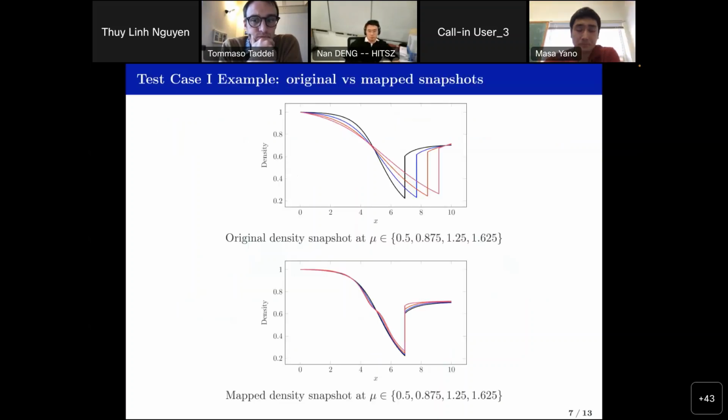If we apply that idea that we saw a few slides ago to this problem, you can see on the top, as you change the nozzle throat area A, the shock moves around. This is an actual example relative to my cartoon on the first slide. But if you were to try to predict anywhere in between those shocks, all you could do is staircase approximate it. Of course, the more snapshots you take, the better that approximation is going to be, but it's never going to get away from staircasing.